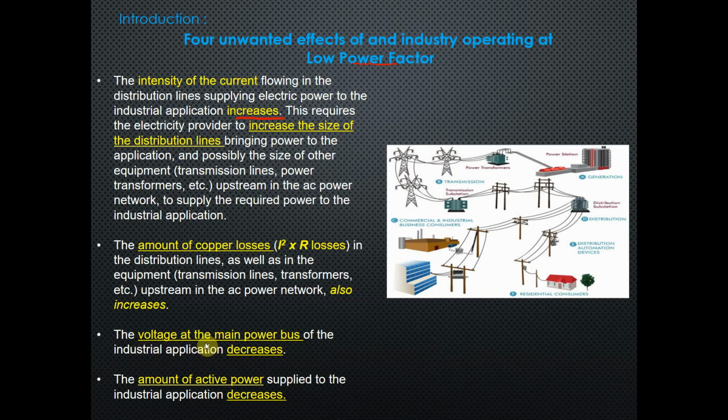The voltage at the main power bus of the industrial application decreases, and there will be a large difference between the no-load voltage and the full-load voltage. The amount of active power supplied to the industrial application also decreases.